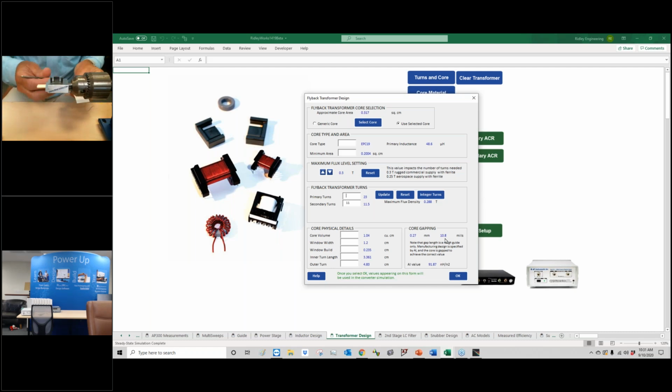So what I do on my prototypes, and this trick in industry, is I just put little gaps in here, little gapping material. And this is a sheet of paper. And Americans out there, a ream of paper is about 2 inches. That's 500 sheets. So each sheet of paper is about just a little over 4 mils. So I'm going to put one sheet of paper in there. I'm going to put 2 sheets of paper in here.